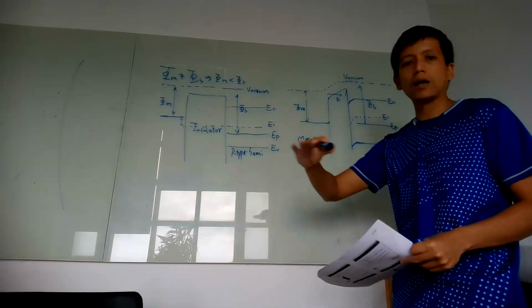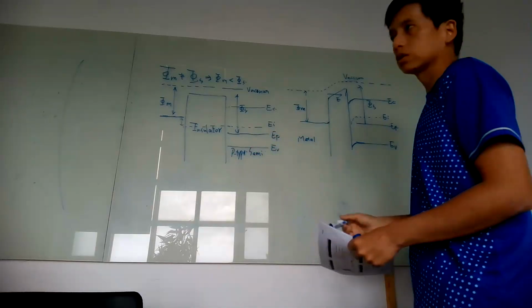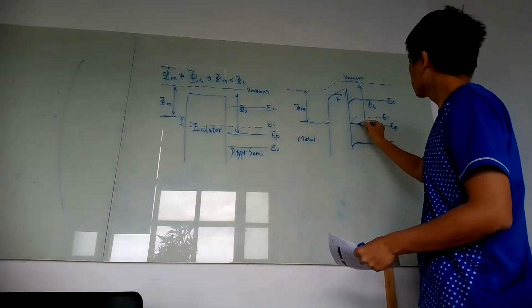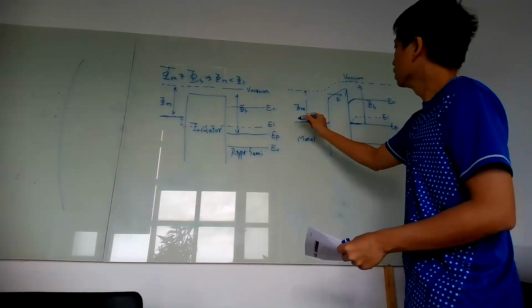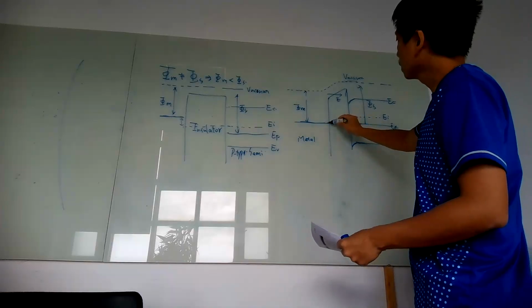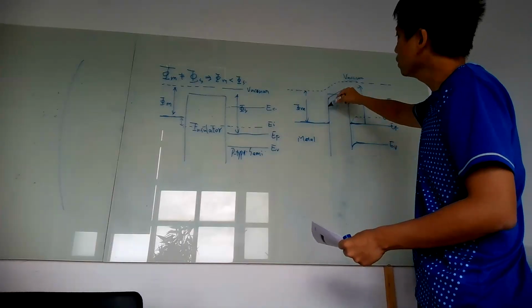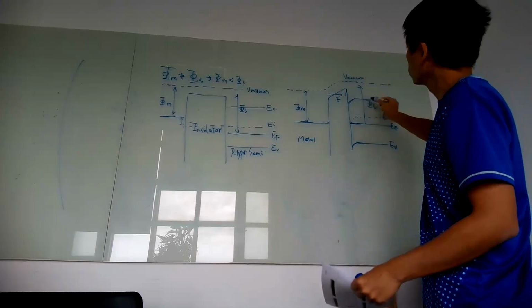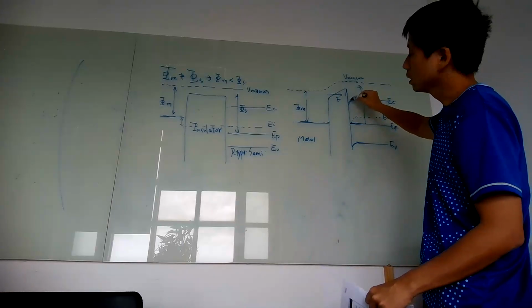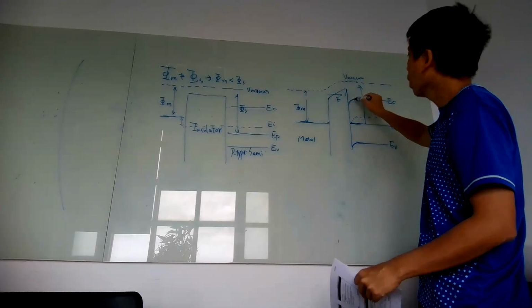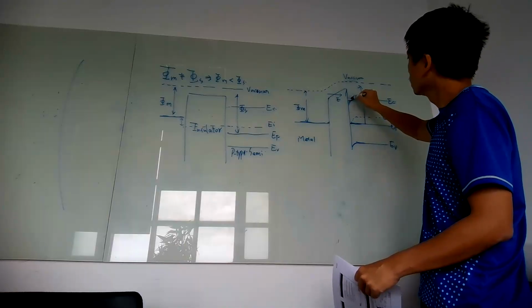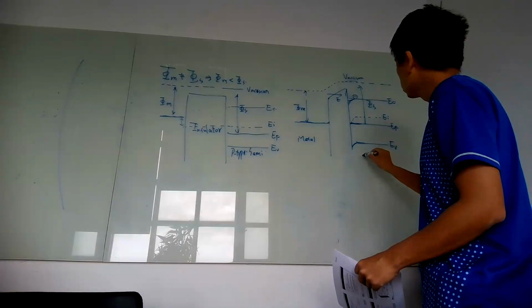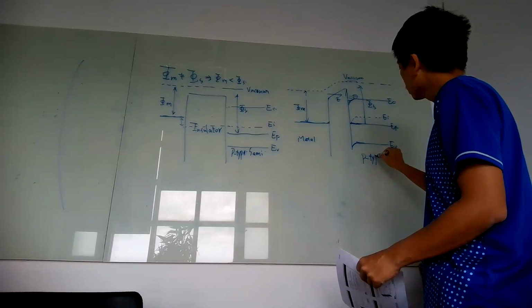Okay, so everything bends down except for the Fermi level, because as we mentioned, the Fermi level is a steady-state level. It should be entirely flat, as long as we do not have extra external biasing. Under that scheme, we get the same Fermi level along the metal layer. And then we get the accumulation of the electric field. When you consider the accumulation of charge, you can consider the charge trapped. Here it will be negative, which is electron. So we get some electrons accumulating here.